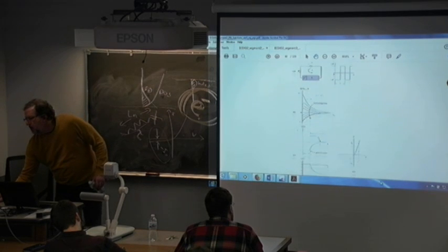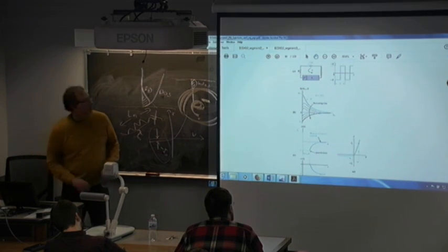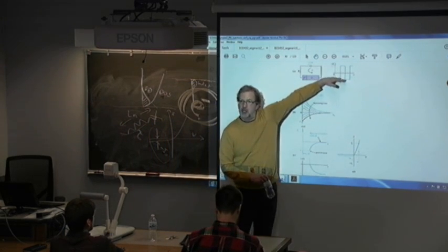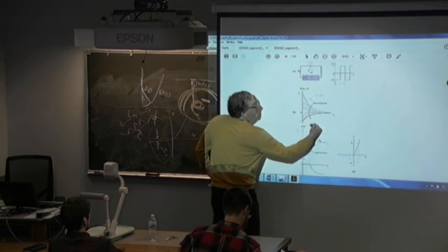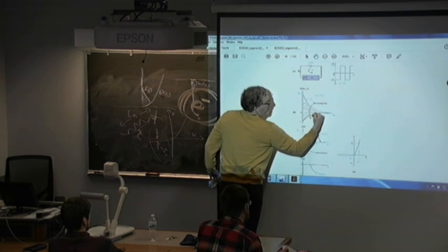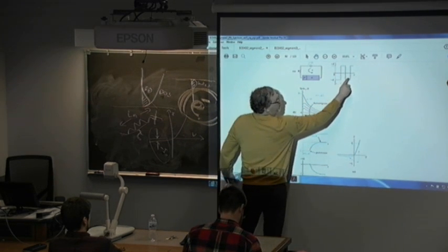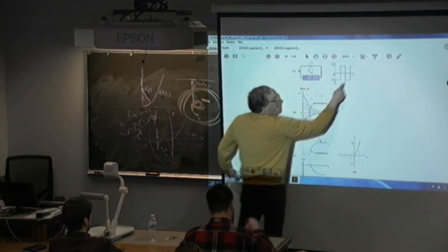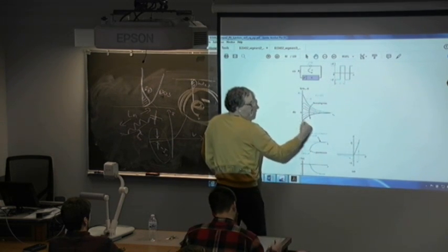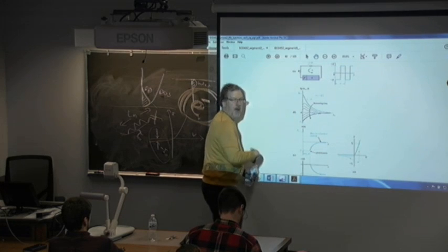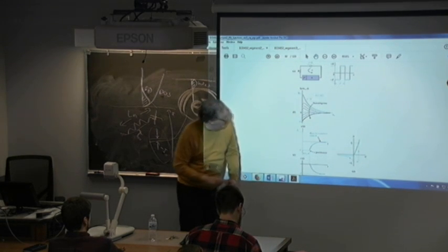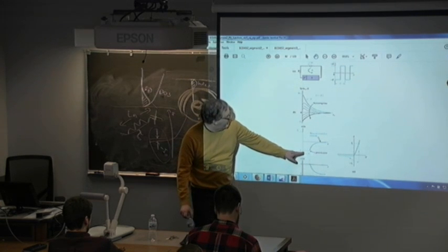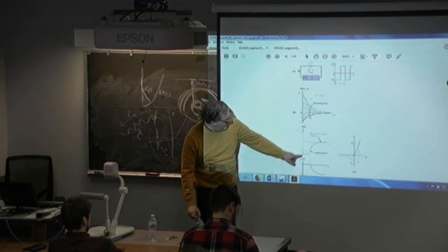So this is maybe a little bit better representation where it's being operated as a digital switch. So I build up under forward bias, and under reverse bias, it's going to fall back down, and so forth. So it's a dog tail wagging up and down, right? But we get this conundrum here where we get this large reverse current momentarily.